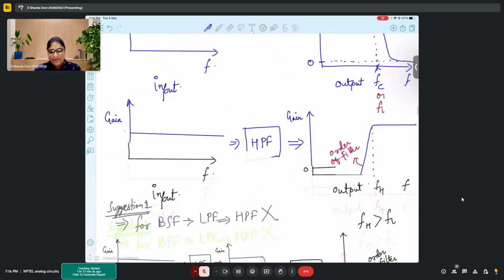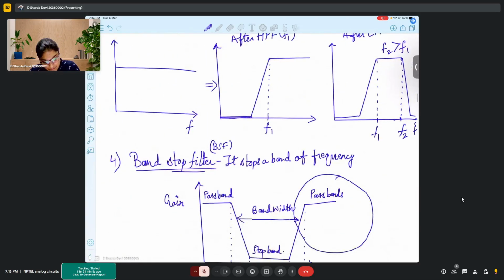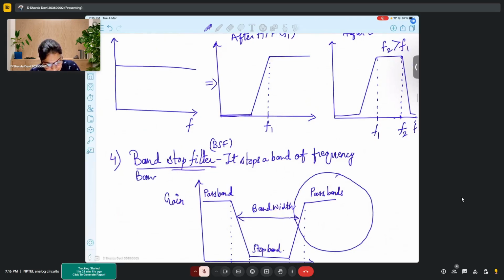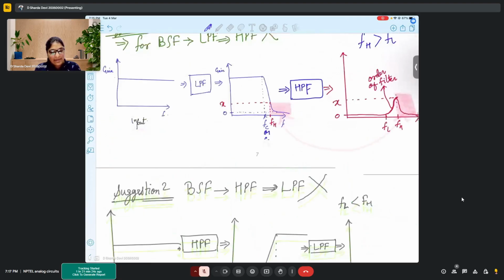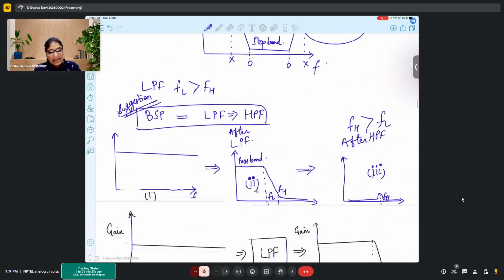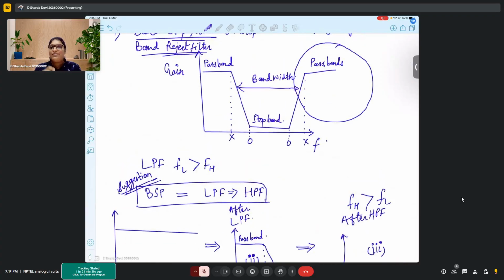Okay, madam. Yeah. So this is also, as well pointed out, this is also known as band reject filters also. And if you make this band rejected band, so we have a band, right, for band rejection. If this band rejection is made very narrow, say if you can eliminate a single frequency, then that particular filter, it is also a band reject filter, but rather than rejecting a band, what you are rejecting is a single frequency.